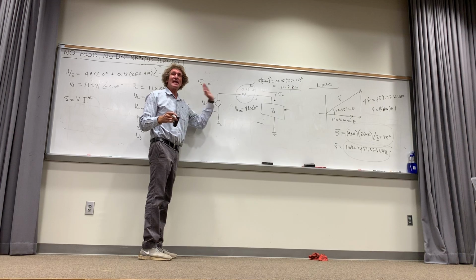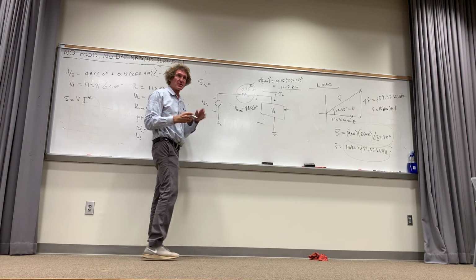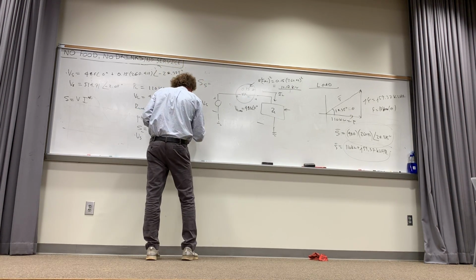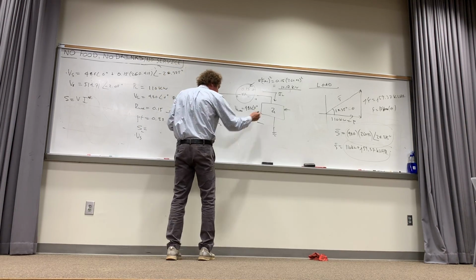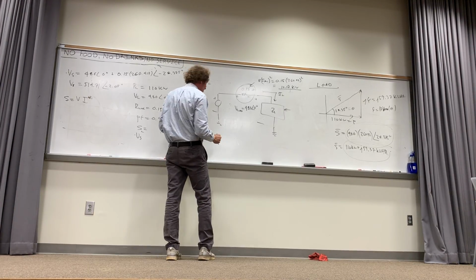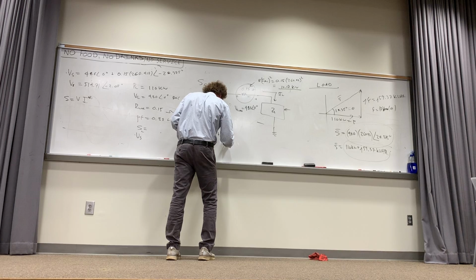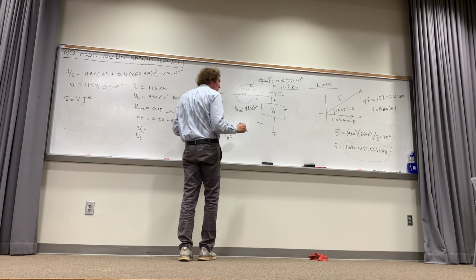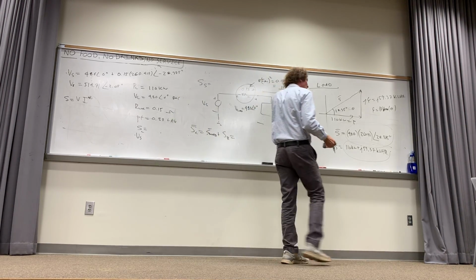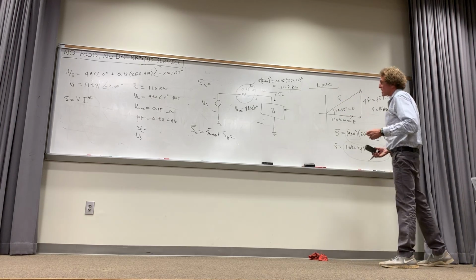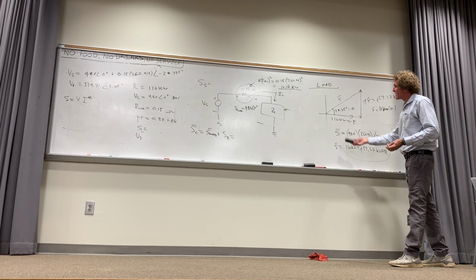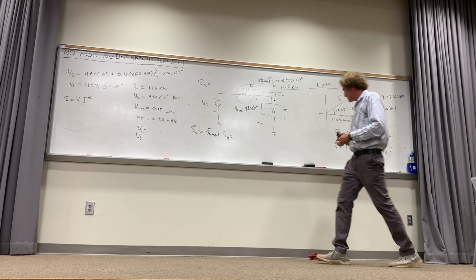Now that means that the total complex power in that circuit, if we use that terminology, and I'll call it S complex, would be equal to the actual complex power of the load plus the complex power of the resistor R. Or if we do it not in polar, but in rectangular coordinates, I'm going to take 110 and add 10.17 to it.